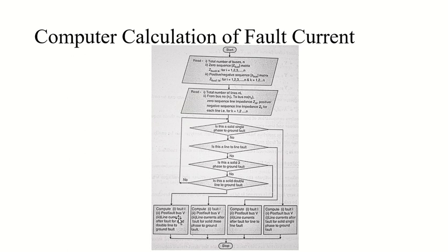After determining the number of lines in the bus, we can say, from bus number i to bus number j, we can calculate the zero sequence line impedance, and then we can calculate the positive and negative sequence line impedances as well, right, for each and every line. First we do it for the buses, positive, negative and zero sequence impedance, and then for lines in each bus, positive, negative and zero sequence impedance.